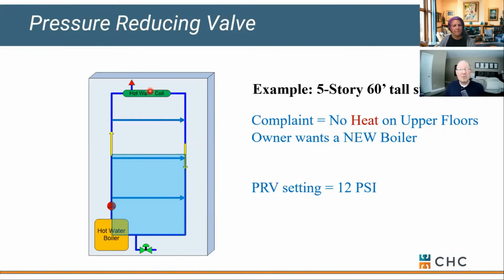Believe it or not, this happens more than you think. People slap in a fill valve, forget that they have to do anything with it, and then wonder why their pump's not running so well, or the boiler's not heating the entire building. Or why they can't balance things, or the system's really noisy all of a sudden. It's because we're circulating water and air, not just water. When you fill your building completely full of water, guess what? It quiets down, you can balance it, you get heat transfer, and people are happy in general, okay? So don't overlook the obvious, which is make sure your pipes are full of water. That's all we're trying to get across here.